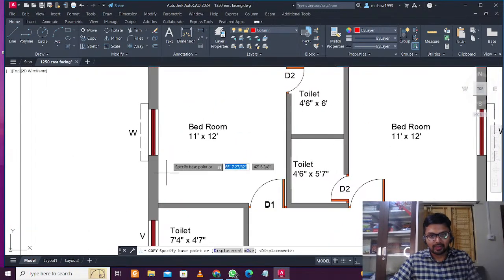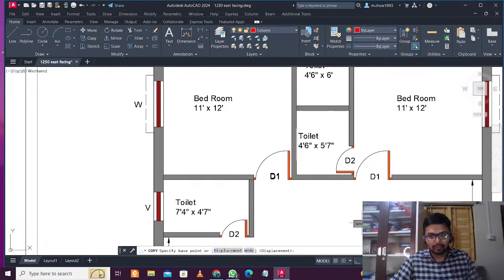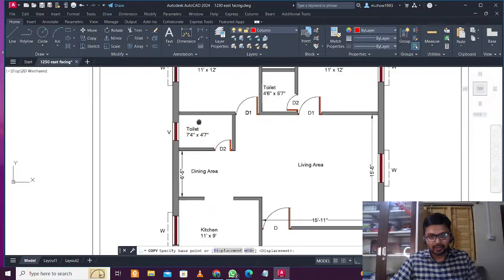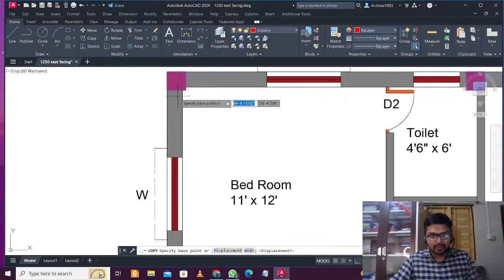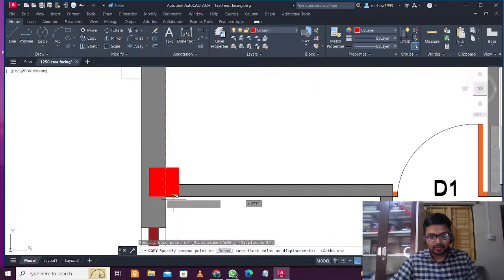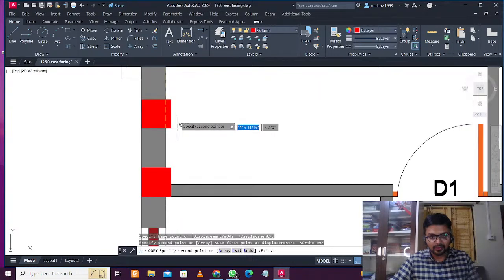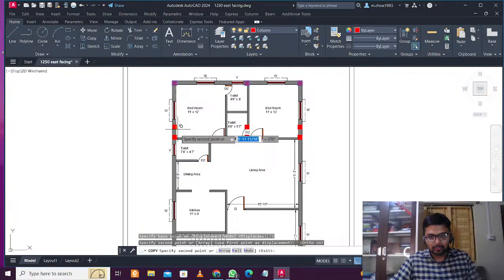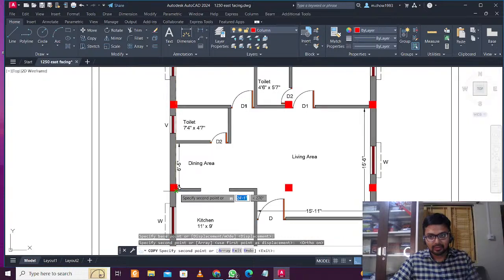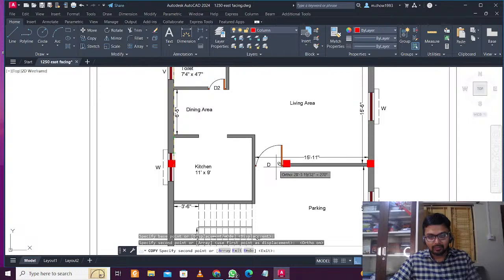We want this to stay inside the room, we don't want to show this in the living area. If you want that, you can just have that. So then we have to select this point and turn on the ortho for this one and place it here. And after that point, let's just place it randomly here, or we have a choice now. We can place it here or down below. So this living area, probably we won't have this space here in the top floor.